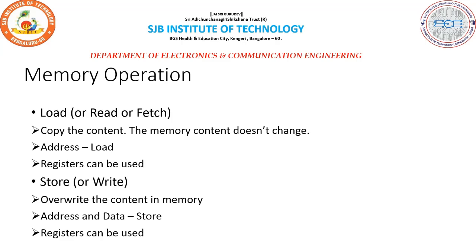The beginning of the string is indicated by giving the address of the byte containing the first character, and successive byte locations contain the successive characters of the string. There are two ways of indicating the length of the string. A special control character that means the end of the string can be used as the last character of the string, or a separate memory word location or processor register can contain a number indicating the length of the string in bytes.